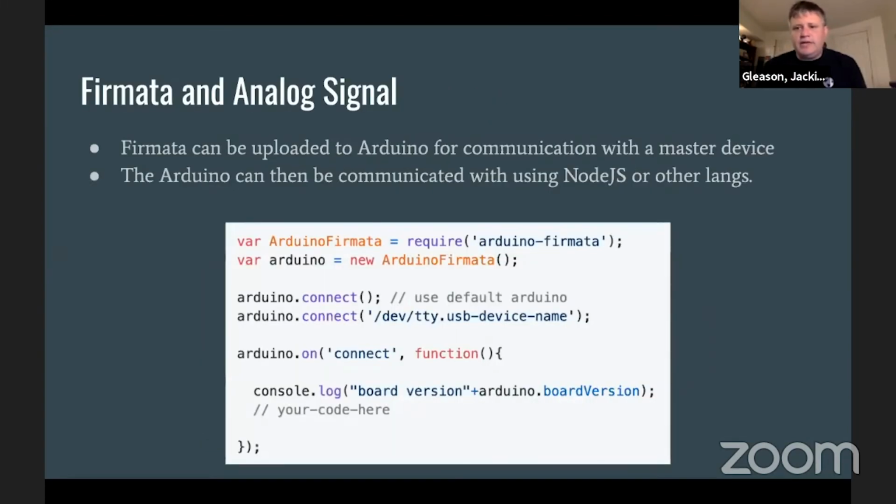Because we're talking about Arduino, I wanted to talk a little bit about Firmata. Firmata is an application that you can install on your Arduino board that allows you to communicate with the actual Arduino itself. Typically you would create a sketch file and upload it to your Arduino board, but with this we want to do something a little more dynamic. Instead of just writing to the serial ports, we can use Firmata to provide a deep integration with the Arduino board from our actual robot application.